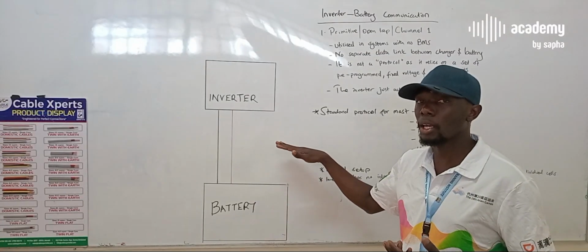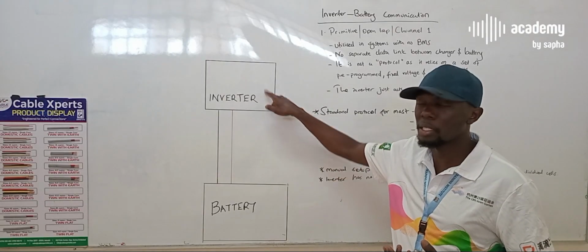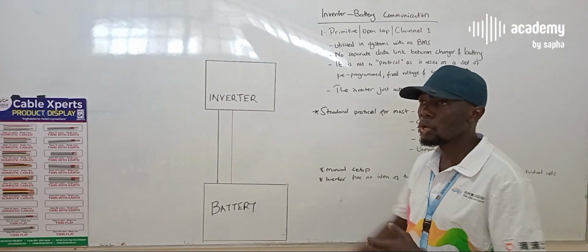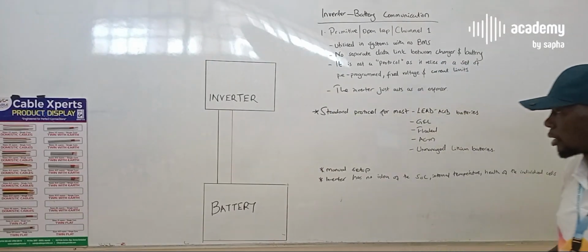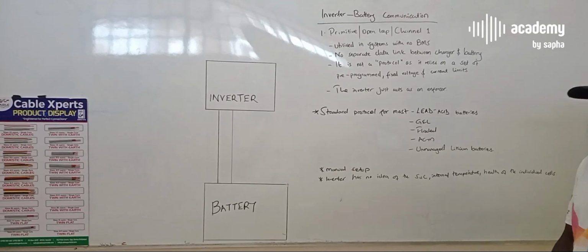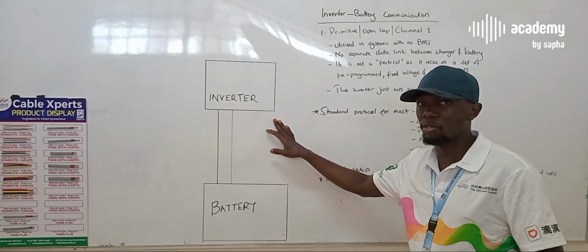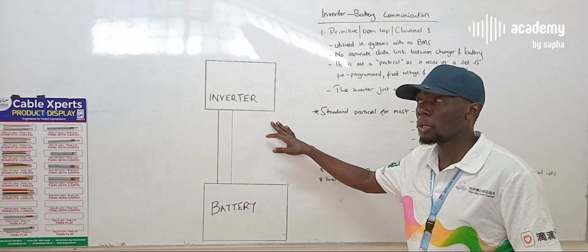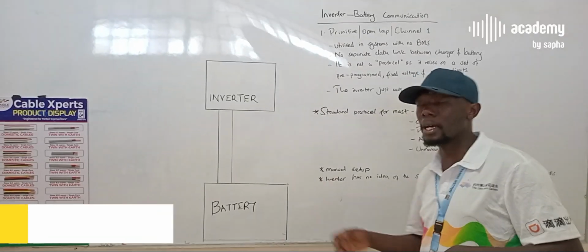If it's not high enough and there's no available sun, the inverter can automatically pick from KPLC and keep charging the batteries. So you have to manually input all this data into the inverter and let it determine what to do. In most cases, the low-end inverters will not have all that provision, but it's just good for you to learn and understand early enough.